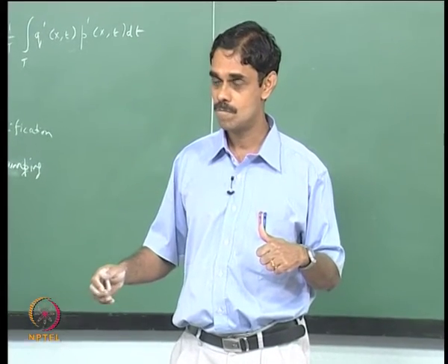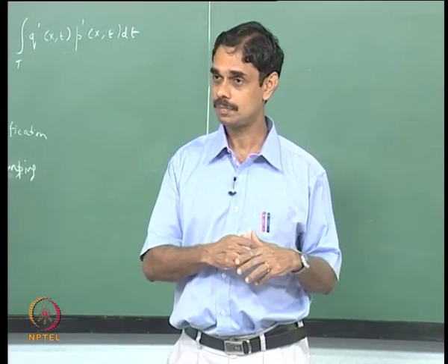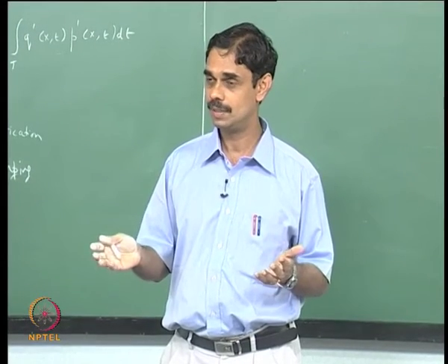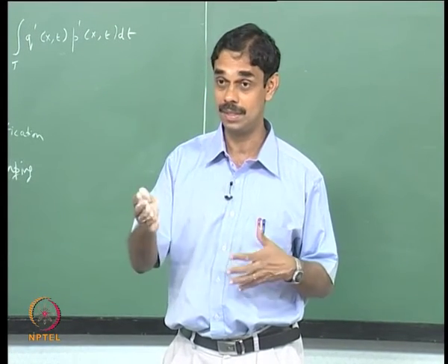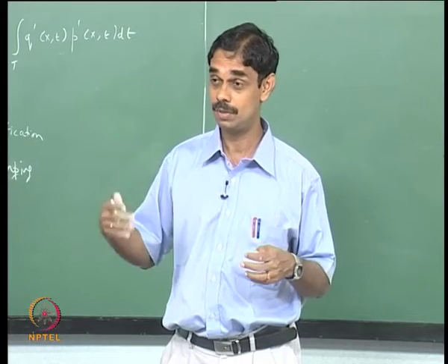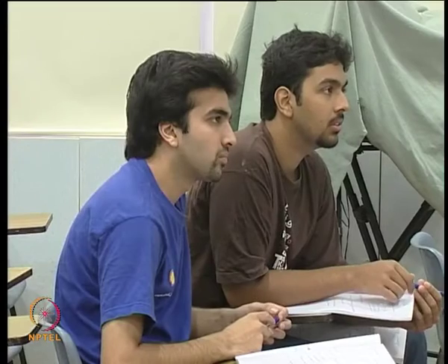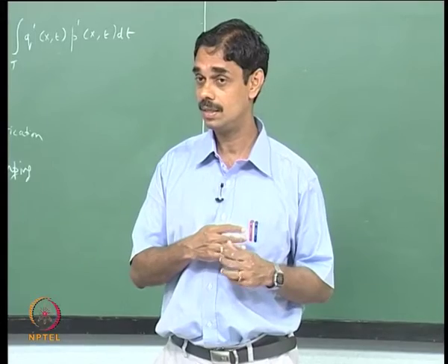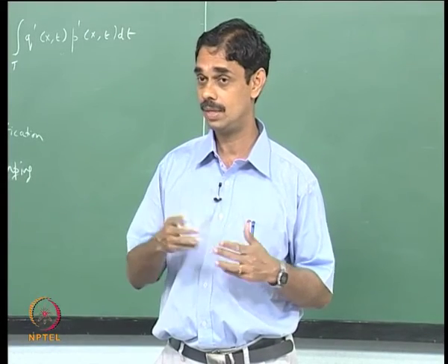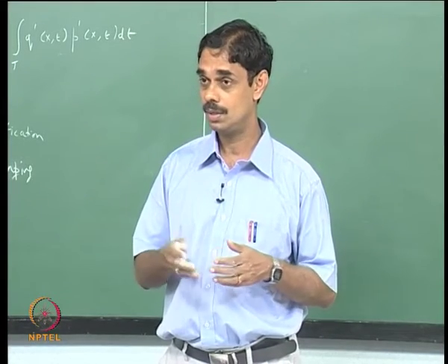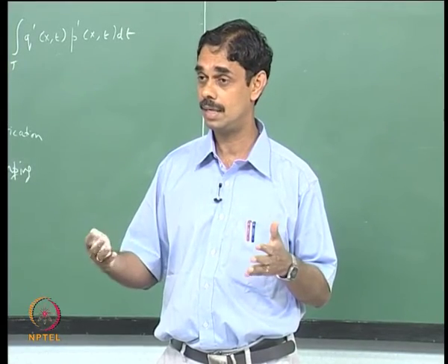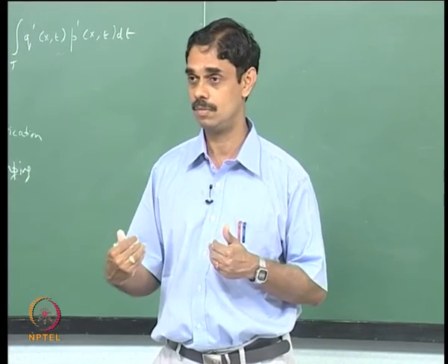So if you have a traveling wave, then you would not get 90 degrees at all, because it is energy flow. There will be admittance, and admittance times P prime squared times area shows the power flow. So as long as the power is flowing, you would not get 90 degrees, and you will have 0 or something in between, and the direction depends on which direction the power is flowing.